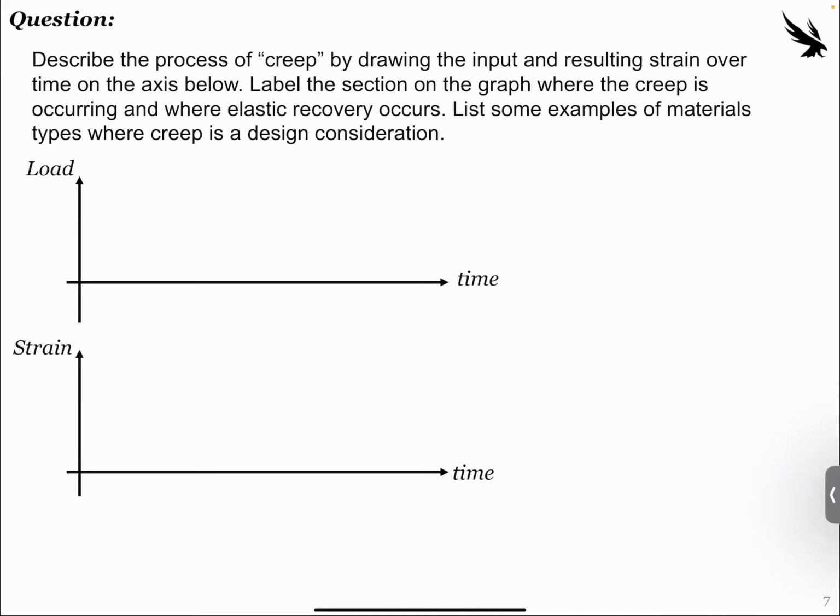So it might be easier to think of some examples of this. Think of like an asphalt material. One of the better examples, which you'll cover later, is consolidation of clays, which, just to summarize that in itself, imagine you have a water balloon that's tied up, and then a bunch of small holes poked in the water balloon. Let's say you put a paperweight on top of the water balloon, and the water can only escape through those small little holes. So the load is constant, but the balloon doesn't deflate right away. It takes time for that water to remove from the holes.